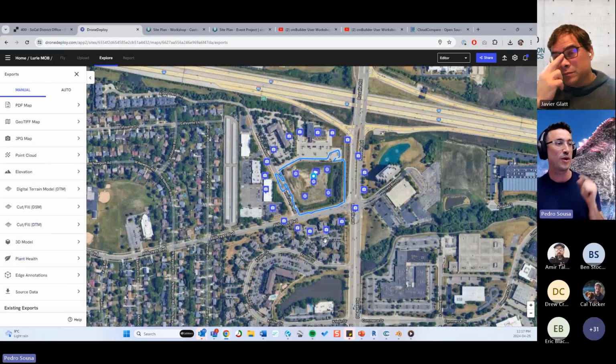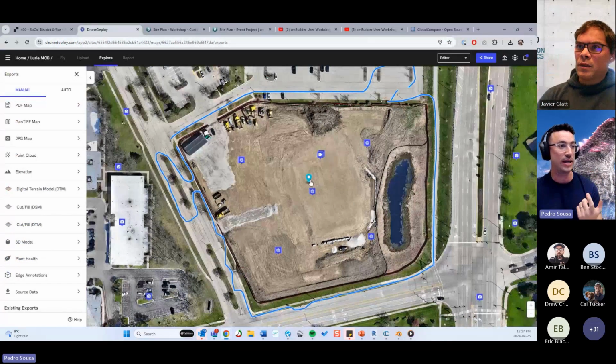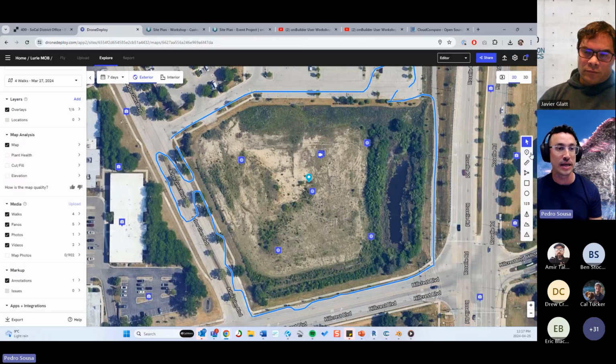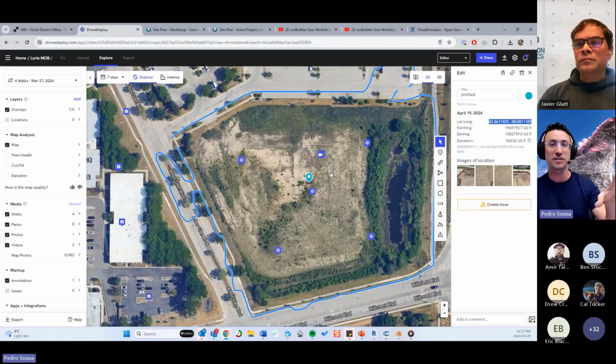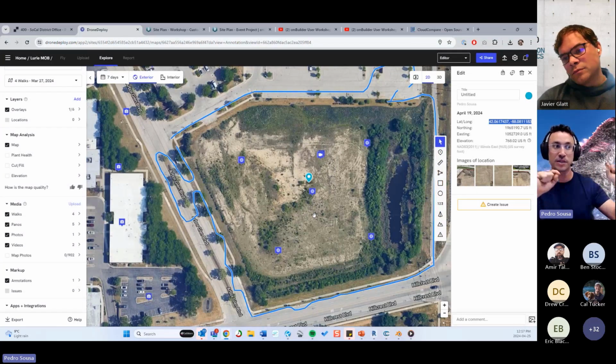One thing that I just found out while I was preparing for this call today about DroneDeploy is that you can create some points in DroneDeploy. You can place a point over here by using this point location. And when you place a point at a location, it will give you the elevation of that point along with the lat and long. It might be interesting for you to check this first, and then when you create your project in cmBuilder, you use the same lat and long to create that project, because then there will be an easier placement, because the origin point of your map and the origin point of this mesh and this surface will be the same, right?